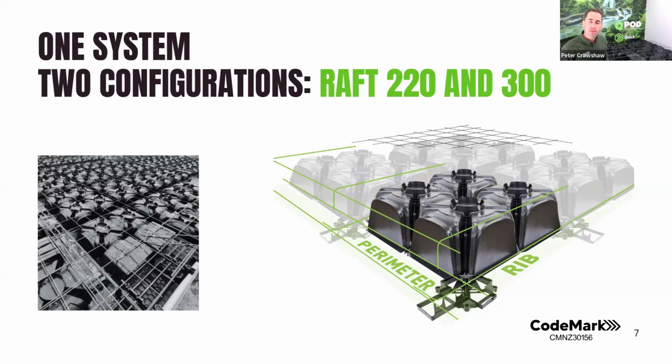Fire rating. So this is a plastic pod in the concrete foundation. In terms of a fire rating for the plastic, PP, which is made out of recycled PP, will burn. But essentially this is a void filler under the foundation, so there's no fire test or rating needed or been done there. I hope that helps on the question there, Sam. Perfect, yeah, thanks Peter.